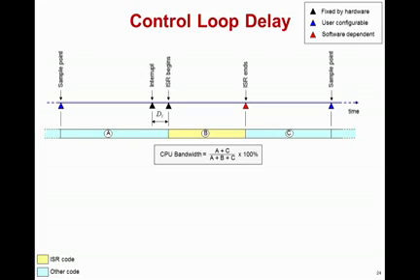The time in A before you get to the interrupt shows what it might take in a processor to convert that analog value to a digital measurement. The delay between the interrupt and the ISR beginning could be due to some code in the system that is non-interruptible or some other delay in the processor itself.